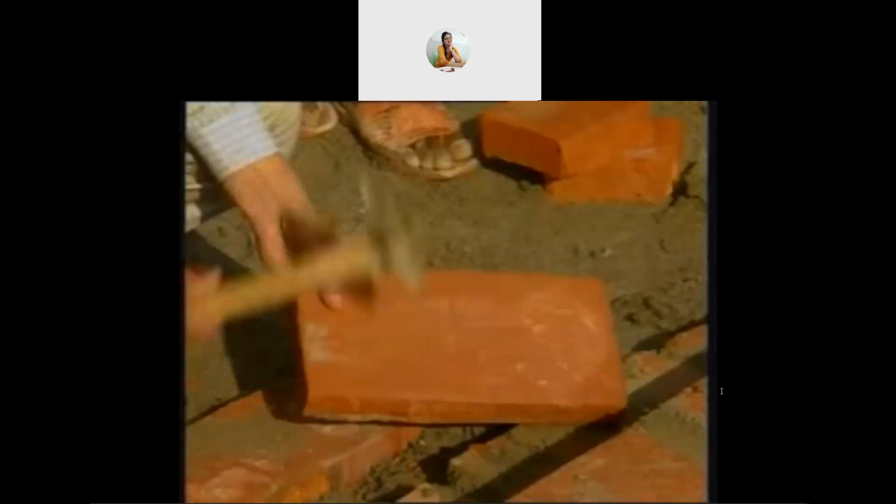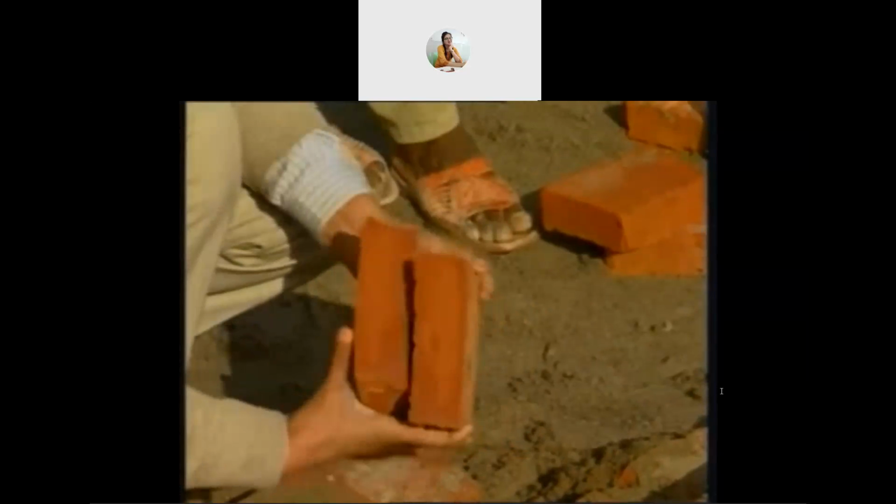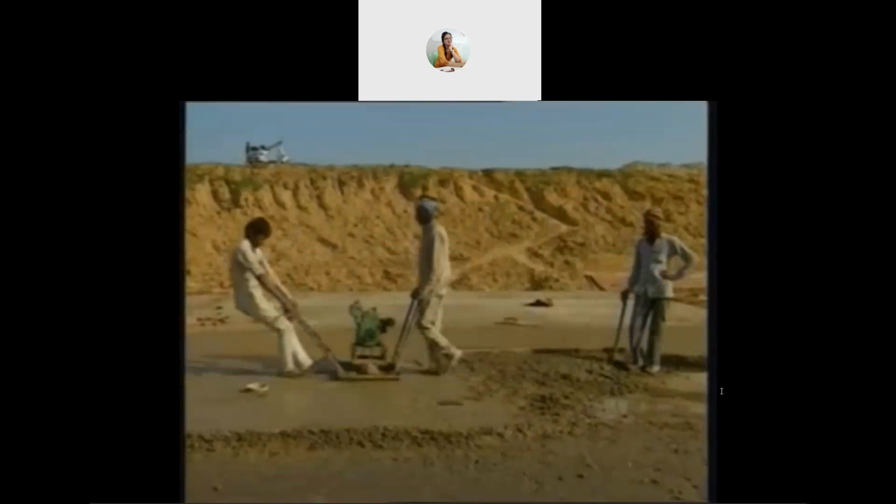Clay tiles are definitely far, far better in respect of abrasion and imperviousness. So now we are doing concrete lining in the bed, and on most of the slopes we are having double clay tile lining. By making a new lined canal, we are saving very substantial quantities of water, to the tune of 240 million cubic meters, which will result in very substantial increases in agriculture production.